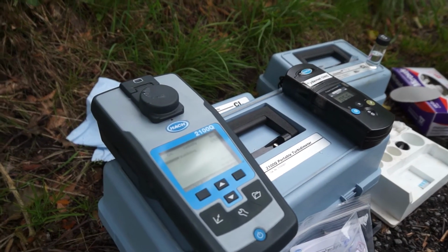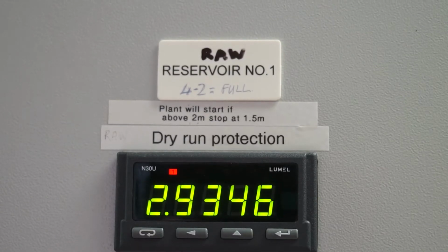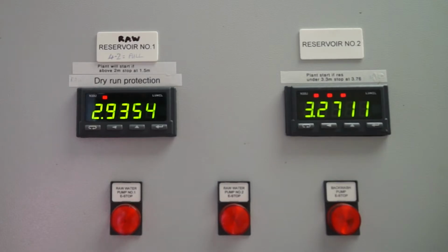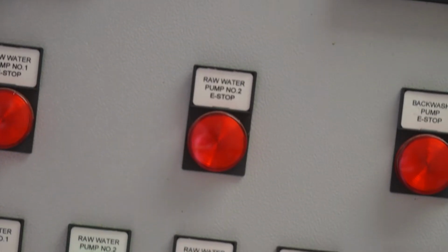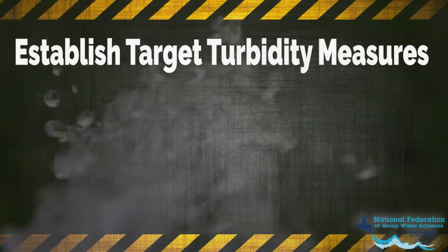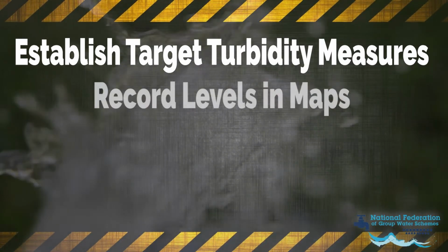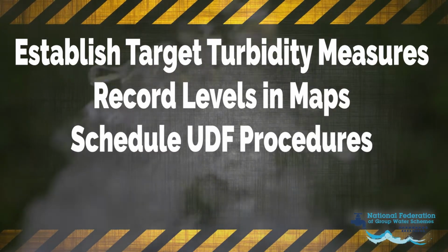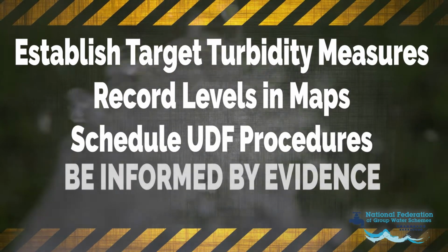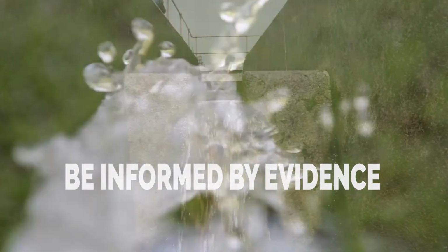To provide further evidence, turbidity levels are a useful guide. Where water is clear of particulate matter leaving the treatment plant, then this figure should remain stable in a clean distribution network. This reinforces the need to establish target turbidity measures at various points in your network. Deciding when to clean your distribution network should therefore be informed by evidence. Measuring your chlorine and turbidity is vital.